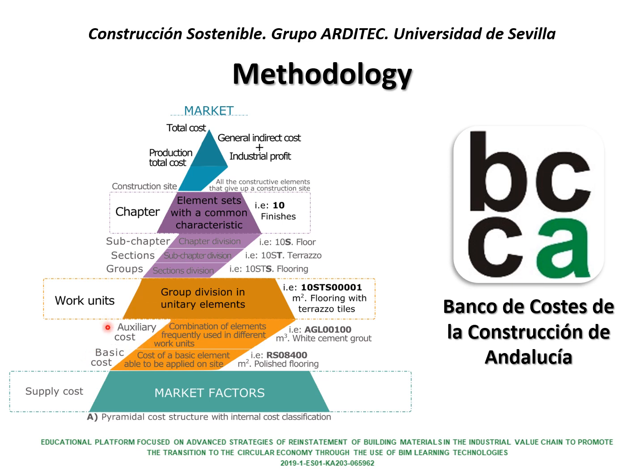And those basic costs can be combined into auxiliary costs. Those are, for example, the mortar, and then that mortar will be employed in a wall, for example. So that's a work unit. The wall in the building, the partition, or the roof, the foundation, those are work units. And those units are also put together depending on their nature and classified into chapters.